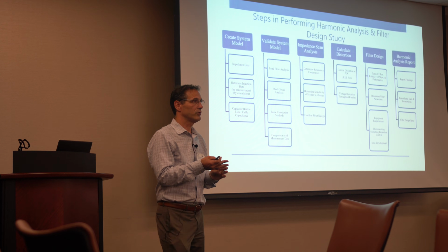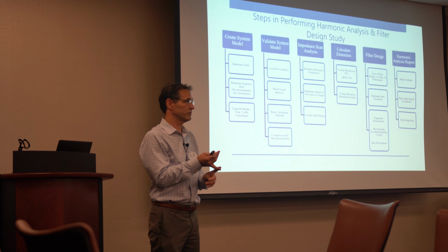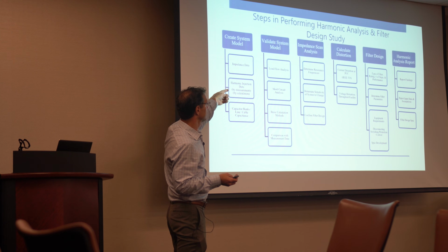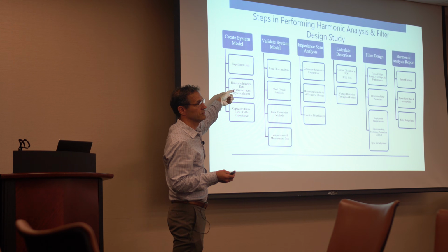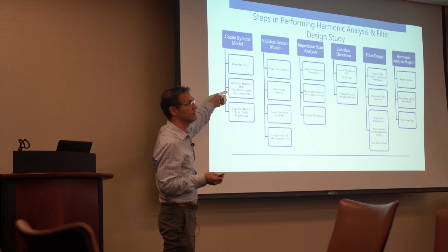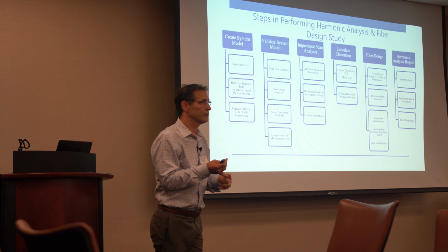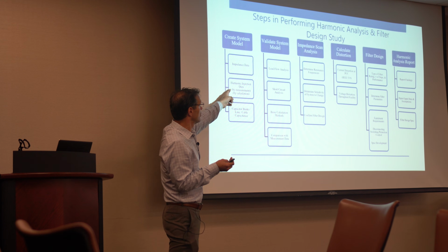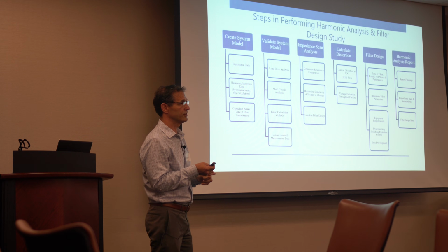So you already modeled all the impedances in the network, and that's what the harmonic analysis model requires. But it requires just one additional piece of data, and that's the harmonic injection data. You've already added capacitors in there for your load flow, so you know your reactive power requirements. But harmonic injection is really the thing you're adding.